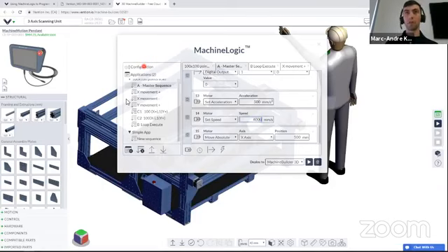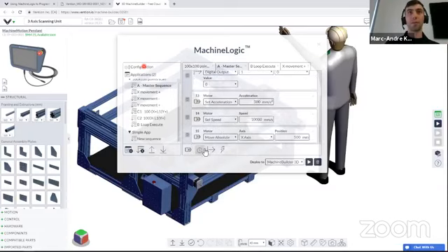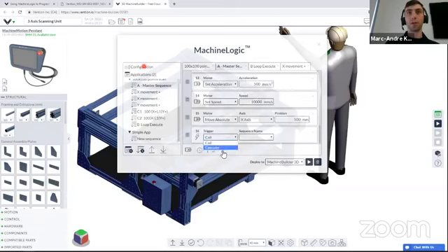Same thing here. If I press enter, it can't support this speed, it's going too fast, so we can go up to 10,000 millimeters per second. So there you have it. You can set the speed, set the acceleration, and move your motor after the output was activated. There you go.